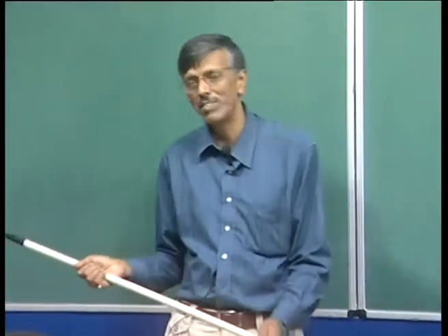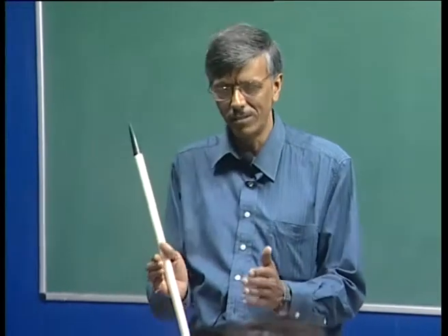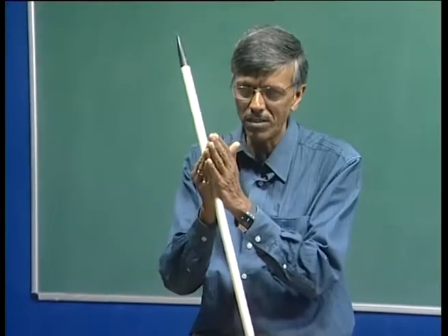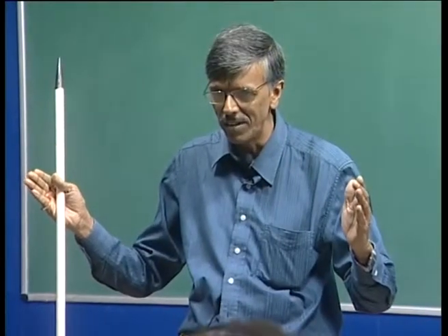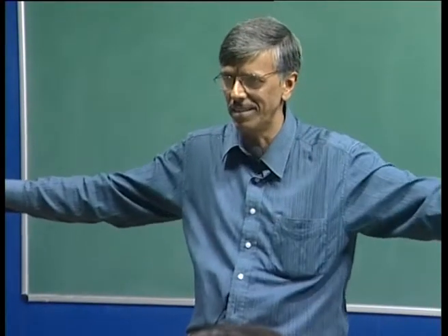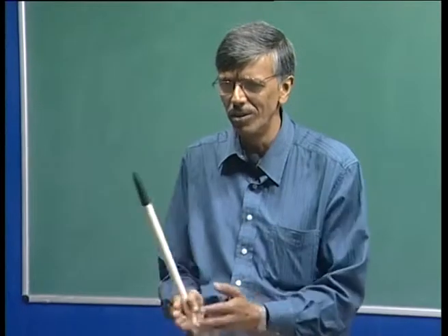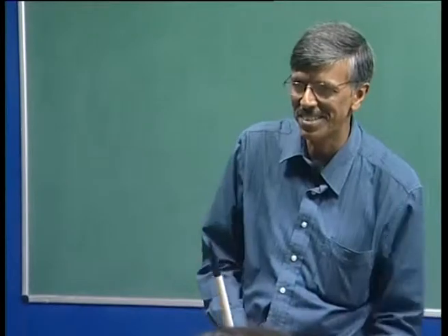That is why you may be seeing a very interesting aspect of flow computations: suppose I have a disturbance field which is localized. Now, if I compute that flow in a domain like this, I get one result. If I do it over this, I get another result. But my disturbance field is located in the middle. What is the problem? The problem is one of periodic extension.